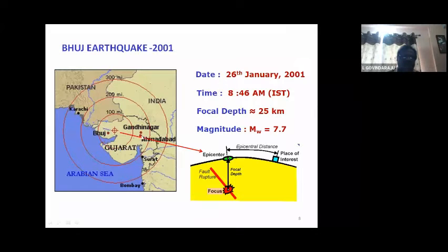So Ahmedabad here, and here is Gandhinagar, and here is Ahmedabad. What is the speciality? Why am I highlighting Ahmedabad here? Because though the earthquake occurred at a distance of 260 kilometers in Bhuj town, there was propagation of the waves, the vibrations from the epicenter location, over a distance of 260 kilometers, traveled to Ahmedabad and caused tremendous damage by means of site effects.